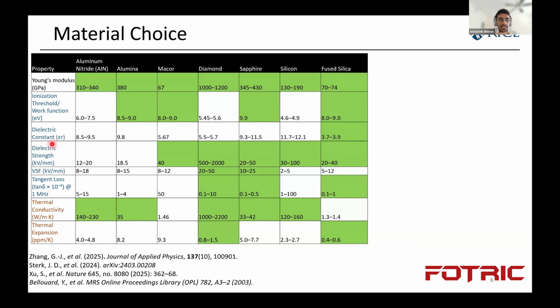And the dielectric constant, a lower value, helps in making sure the trap capacitance itself is low, and it reduces the power demand from the trap. So this is how it scales the power dissipated on the trap. C is the trap capacitance, so a low dielectric constant reduces the power requirement for the trap, with lesser overhead on the dissipation.